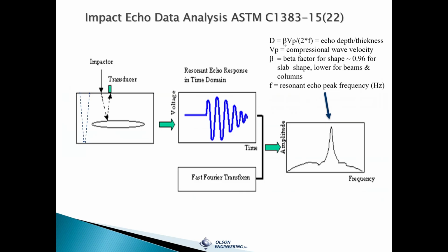So when you hit it, you get resonant echoes. It's a resonance test. There's an ASTM standard for it. We were probably the first company, as far as I know, to ever do the test when it was first researched by Cornell University and at NIST also. Dr. Nicholas Carino was funding it and very involved in it. It was research by Mary Sansalone when she was a PhD student at Cornell. We did the test very early on, I think as far back as 1986. It was very similar to foundation testing we were doing, so we started doing impact echo a long time back.